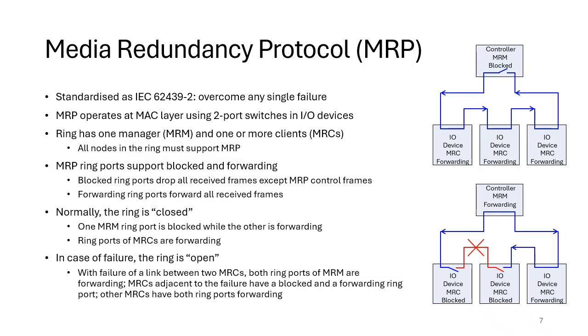You don't have to worry about that because the GSDML file handles that side of it. However, if you do look on the network, you will see those multiple MAC addresses. Now, another point is not every I/O device has those 2 ports. Some only have 1. If you want to do MRP with a device that's only got a single network port, then you would have to use an MRP switch, and then you would have an additional single point of failure of the switch and of the single cable that connects to your I/O device.